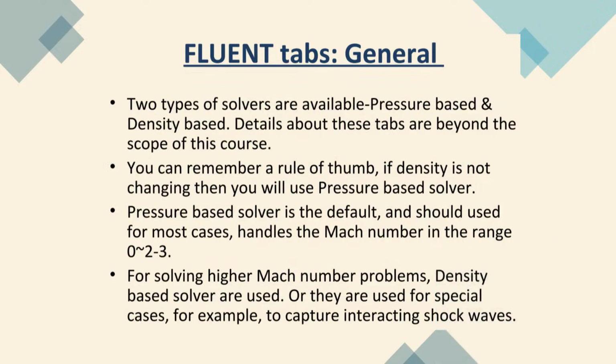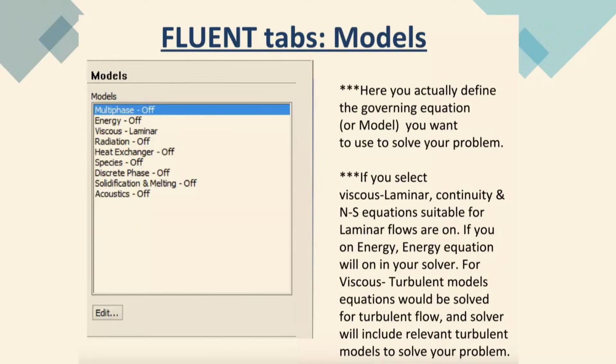I already discussed that, so I do not need to go over it again. Now, this is very important: what equations you are actually going to solve. There are a lot of equations here, as Professor Chakraborty already mentioned this morning. You can see multi-phase: is your problem multi-phase or single phase? You have to check before you start. We are not dealing with multi-phase here, we are dealing with single phase, so that is off. Off means it is not activated for your problem.